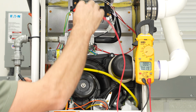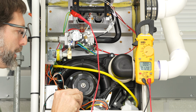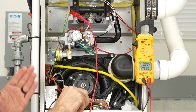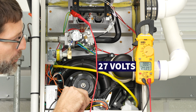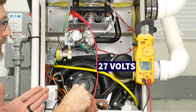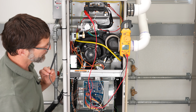So if we have a problem, we're just going to put one probe on the ground. We're going to measure for voltage in alternating current. It's going to be a 24 volt signal. So anything between, say, 24 and 29.5 volts is considered 24 volts. So we're measuring 27 volts there. And I'm going to go on the lower tab, and we also still have 27 volts. That means that that switch is electrically closed. It shouldn't be. So let me show you what you should be measuring.